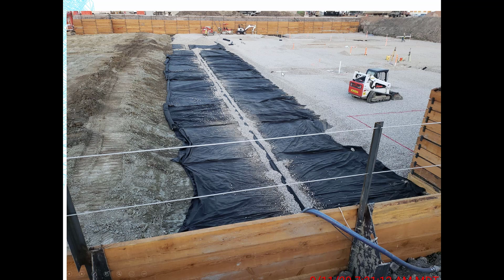then doing a trench for the dewatering system, putting in the Mirafi fabric, putting in the gravel to slope that pipe the right way, and then putting the pipe in more gravel, and then burying it with gravel. And in this photo, you can kind of see people then falling back behind that team doing piping that is more on the surface. So deepest to shallow, it went in deep. And then they put in the gravel. Now they're moving some gravel away so they can finish off the rest of this piping.